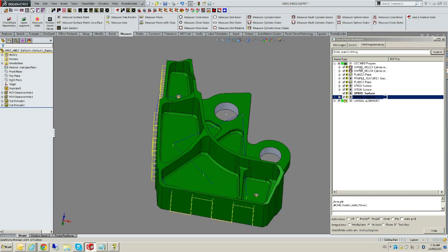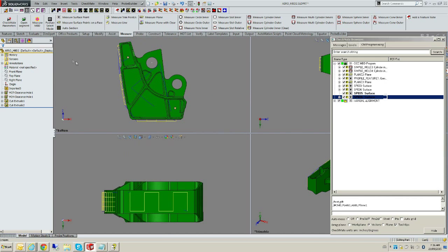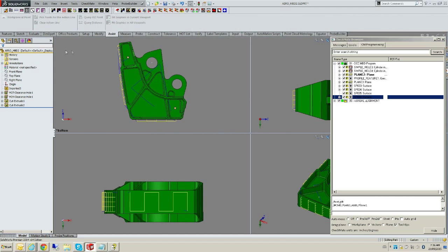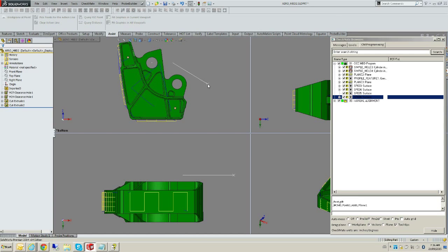What it does is basically add a probe move on either side of the measurement. There are a few different ways of doing it, but my favorite is going up to the work plane, so I'm just going to show you how to do this. We're going to go to our special views, and I'm going to go to the assist. We're going to say work plane at point, and I'm just going to go to this bottom view and pick a work plane point just above the part, click on the top view to finish the command, and now I'm just going to go to a single view.